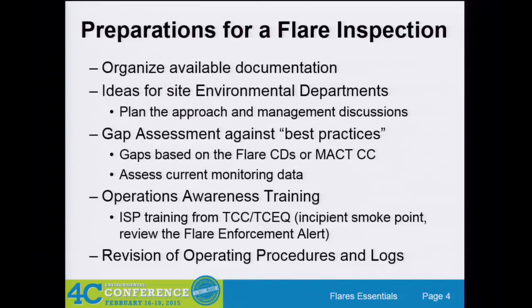Okay, preparations, and this is for, we say, a flare inspection, but really it's also for a 114 request. Go to your plant, find your information. Find out what instrumentation you have on your flare. What data do you have? Where is it stored? How can you get it? When you get a 114 response, it comes with a standard 30-day period to get those responses in. We've seen upwards of 30 questions, going back 5, 10 years. That's a lot of information to pull together in 30 days.